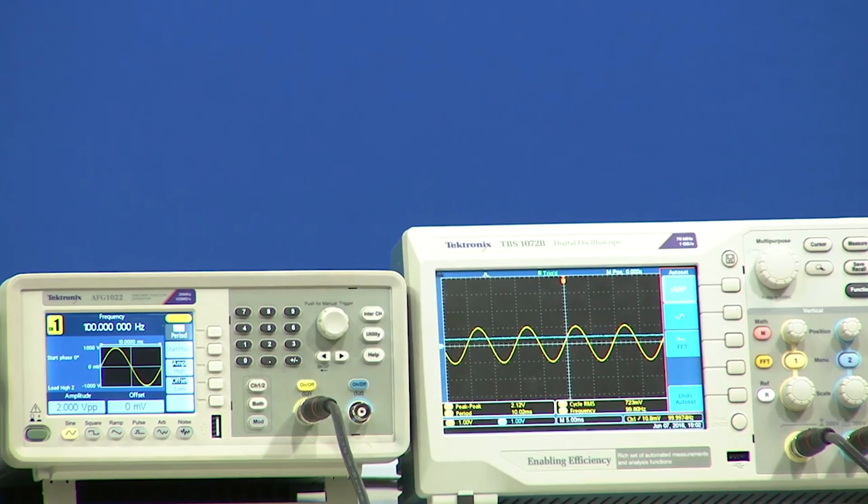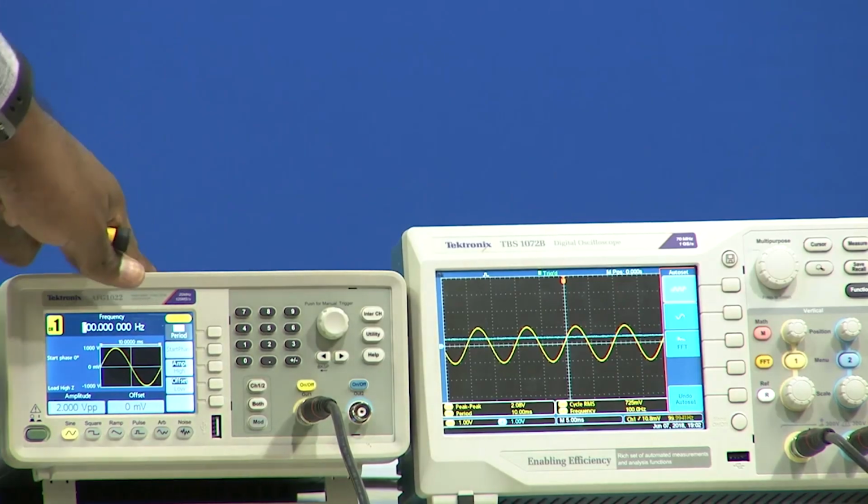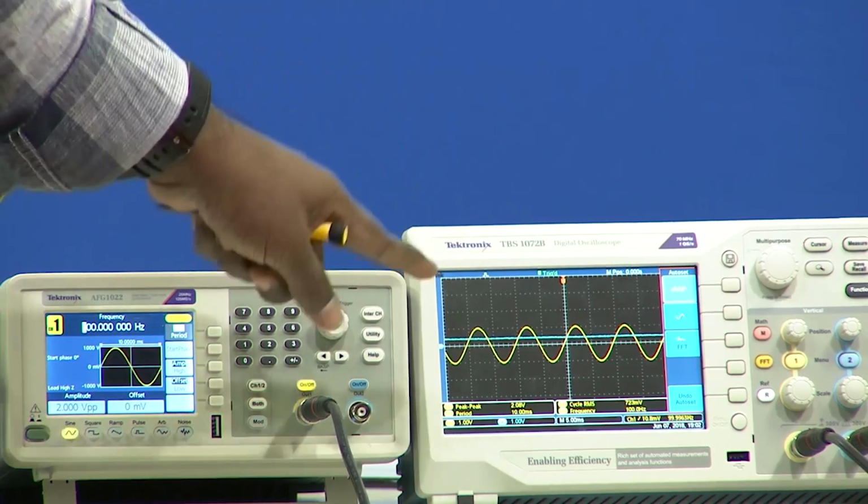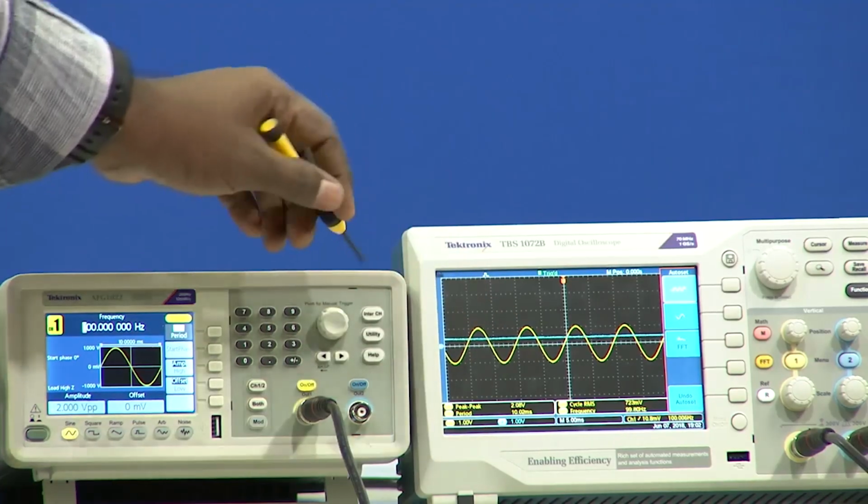The reason why there is a difference between the calculated value and the experimental value may be because of some loading due to the previous stages, or because of the tolerances. Since we have used 1 mega and 2 mega resistances, the 5% tolerance is enough to change the complete resistance value to other values. So because of the tolerances and the previous loading stages, it is going to show some other threshold value.